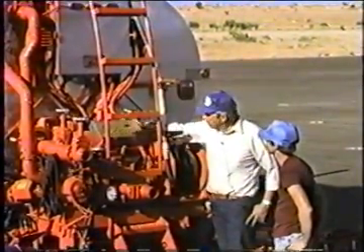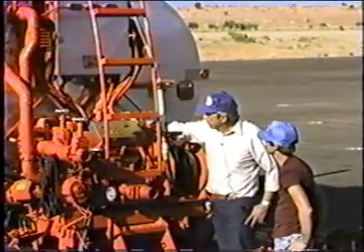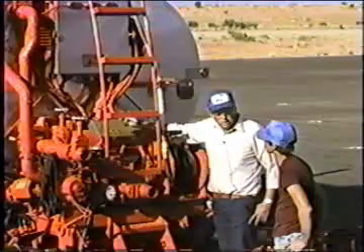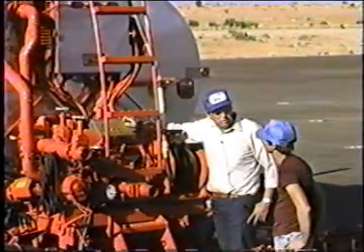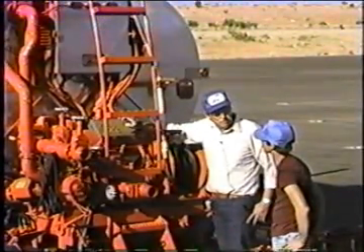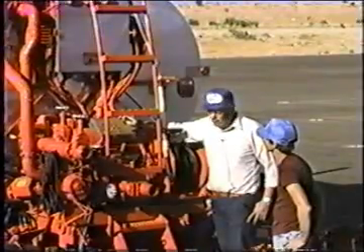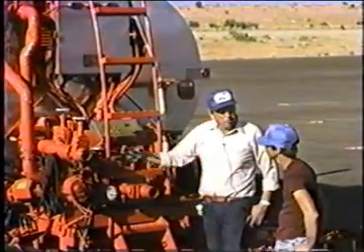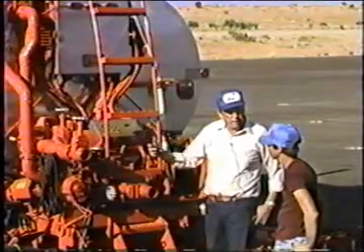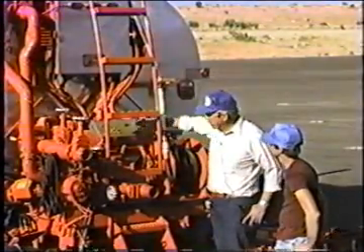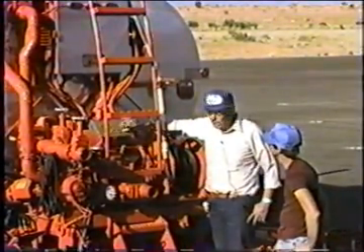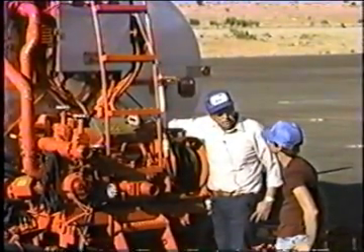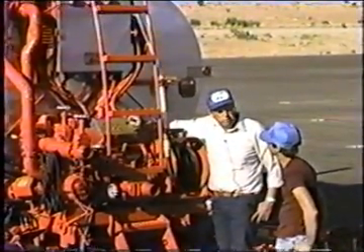Then you can come to the back of the truck. You can turn this to the direction you want, that is forward or reverse, and you can control the speed with the volume knob here. Okay, when you're done, and you do that sometimes for clean out, sometimes for odd pumping jobs, you can control the pump back here. When you're done controlling it back here, leave this turned clear down, and in the neutral position. If you don't, well, then you don't have manual control at the front.